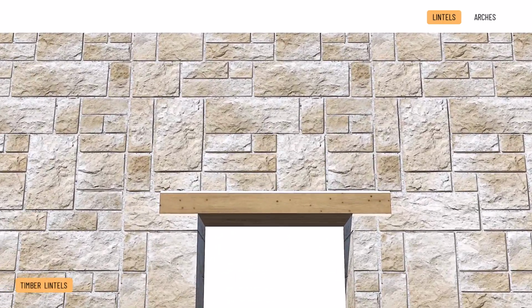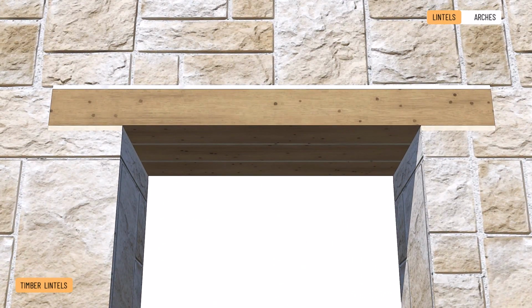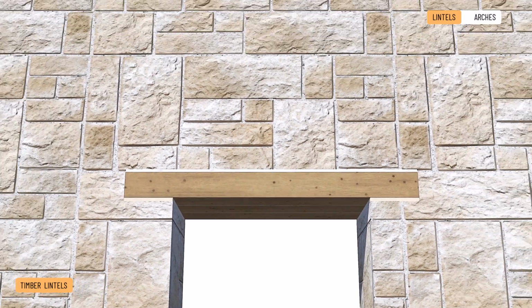Timber lintels. In contrast, timber beams are considered highly efficient as bent structures, and therefore they have traditionally been the most commonly used straight-lined lintels. Timber lintels are square cross-sectioned, hewn or sawn wooden beams laid in mortar or mud mortar on both sides of the opening, giving the lintel elements suitable bearing. For wider walls, several beams should be placed side by side, leaving ventilation gaps between them to prevent decay. Lintels were also exposed to extend their lifespan and were less frequently whitewashed, painted or timber-clad.